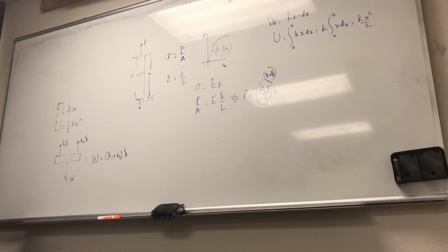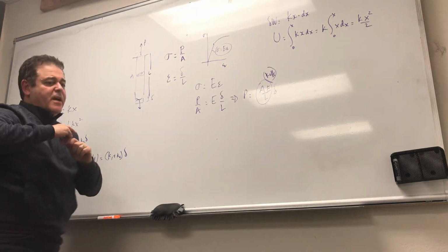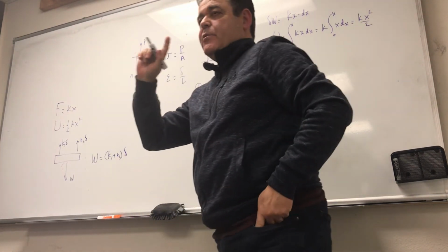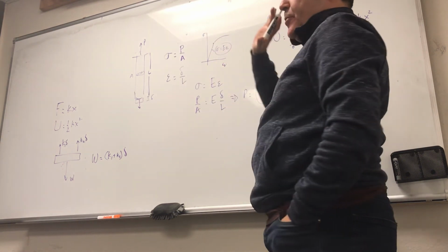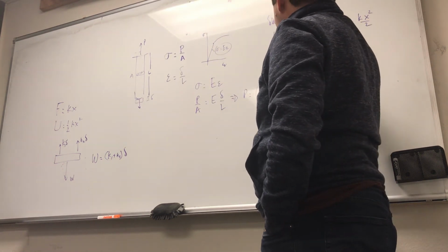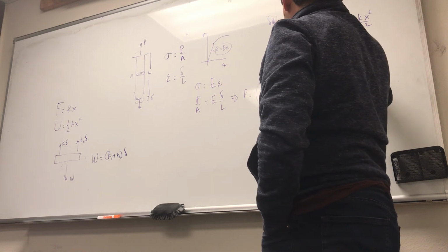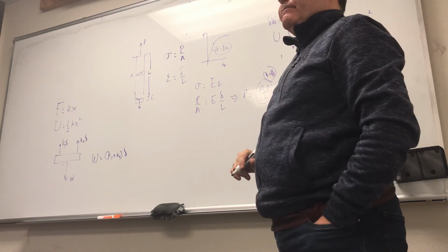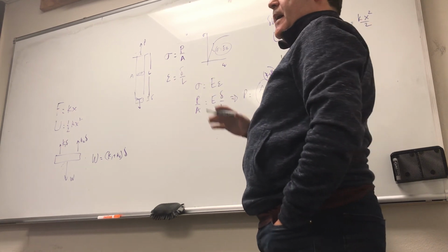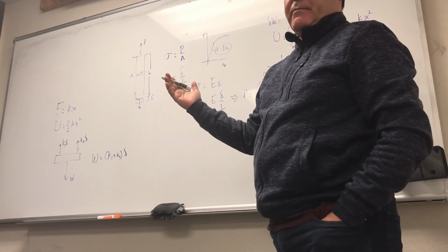Assuming that the angular displacement of the bar is really small. By the way, in vibration and many other things, anytime you are told that you have a small angle, what approximation are you implied to make? The only approximation you have to remember is that sine of the angle is approximately equal to the angle, and the cosine of the angle is approximately 1.